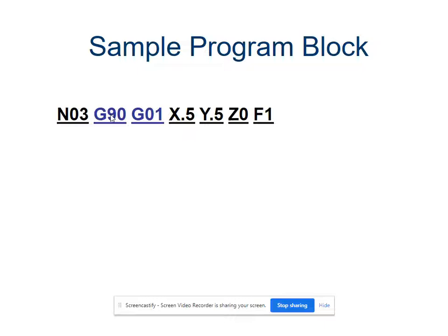Now, if I want it to go to 2, 2, and this is all that geometry stuff that you've learned in school, practically applied, it's going to think to itself, okay, 0, 0 is over here. 2, 2 is over 2 and up 2. So it's in absolute. It's not moving from the 1, 1. It's moving from the 0, 0. So it's counting from the absolute coordinate of this thing. Travis, G01.